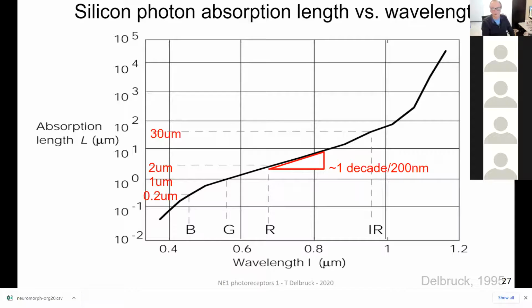So it's hard to capture deep infrared because the photodiode's right at the surface, and most of the light is actually absorbed deep in silicon. So you have to somehow make the silicon very, very pure so the electrons can diffuse up to the junction and get collected.